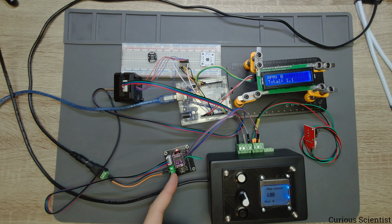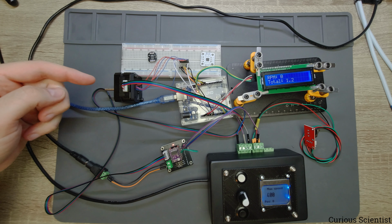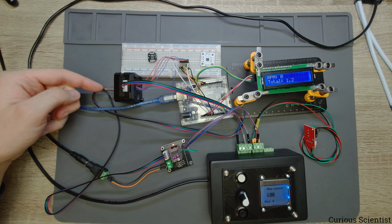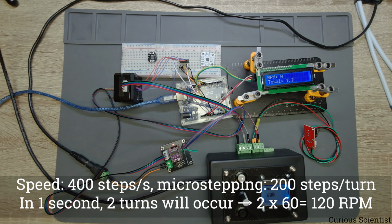And since I have the microstepping set in a way that I'm using the full steps, which is 200 steps per turn, then this means that in each second I expect 2 turns on the main shaft. And then if we translate that into RPM, that is 2 times 60, because we have 60 seconds in a minute, then the RPM should be 120.